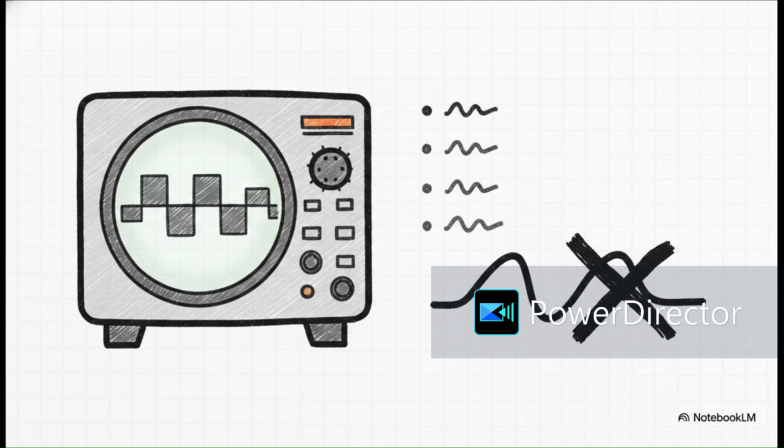And your golden answer is PWM, pulse width modulation. By modulating, or basically changing the width of the electrical pulses as it switches that DC voltage on and off, the IGBT can precisely control the average voltage and the average frequency delivered to the motor. It's pretty elegant, really. Wide pulses mean a higher average voltage, narrow pulses mean lower. This is exactly how we manage speed, and dealing with the resulting harmonics is a huge part of drive design.